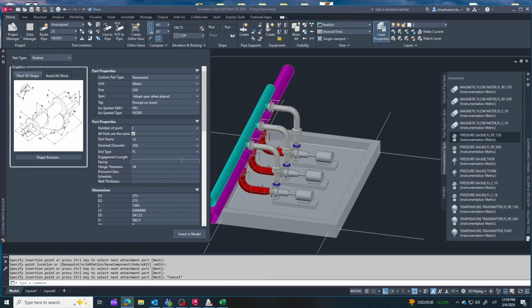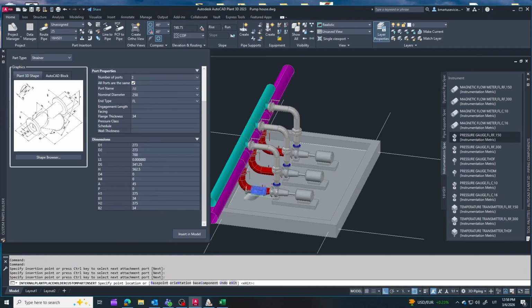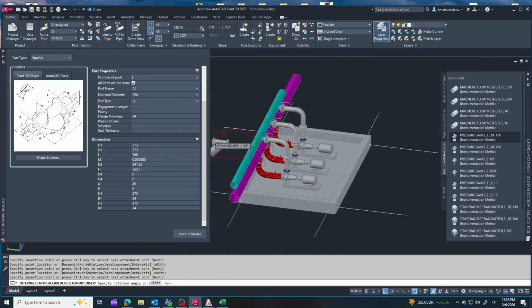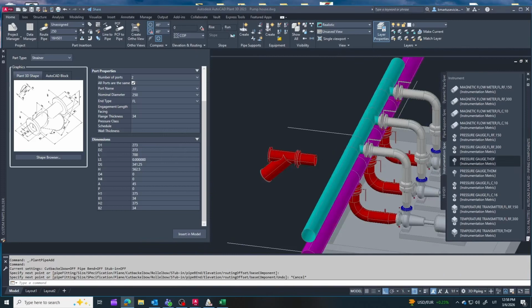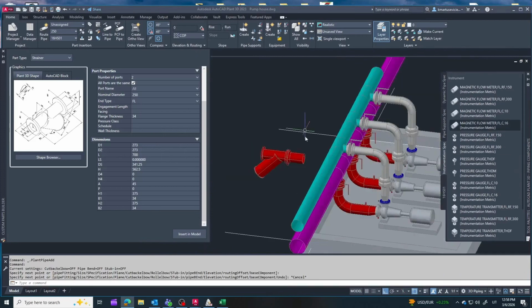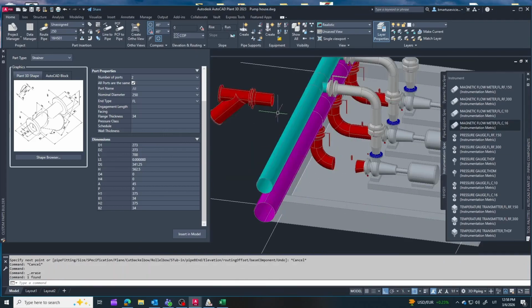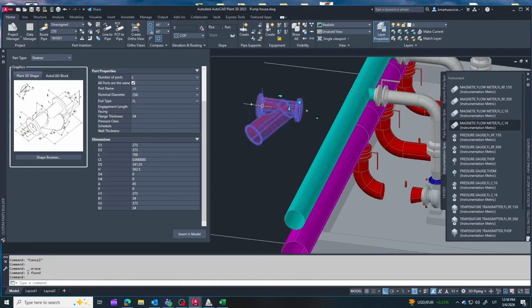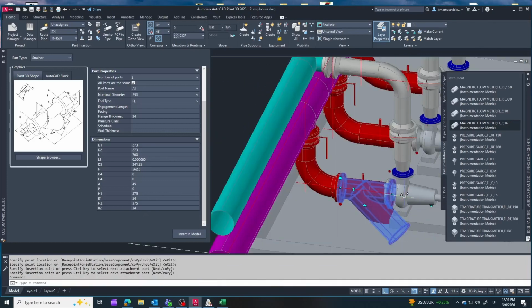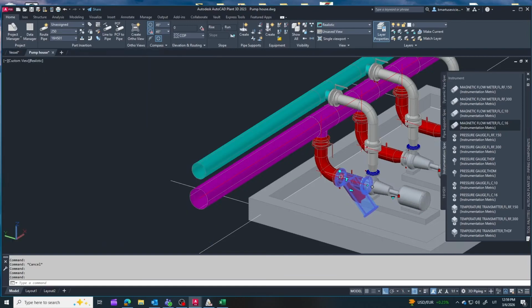I will slightly modify the strainer geometry because the default model generated by the program is unrealistically large for this layout. Do not forget to orient the strainer bucket toward the correct side. I have heard cases where strainers were installed backwards because the correct orientation was badly indicated in the drawings.